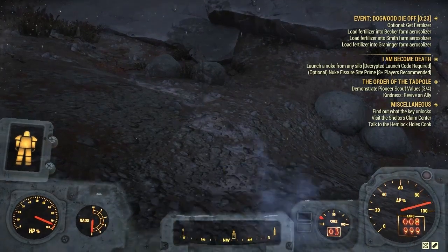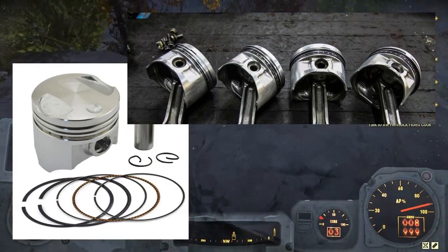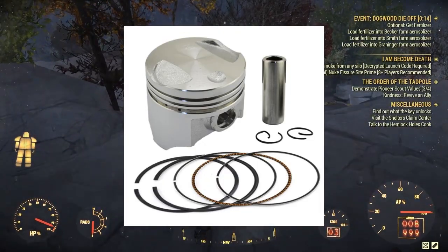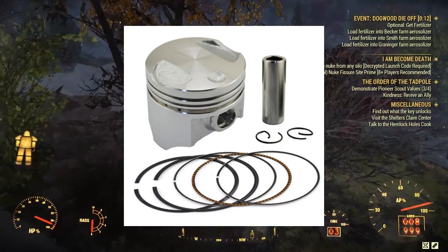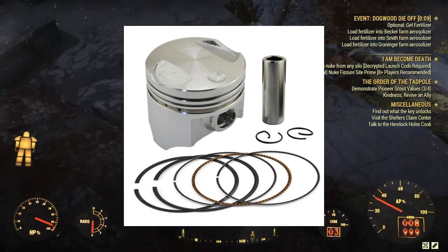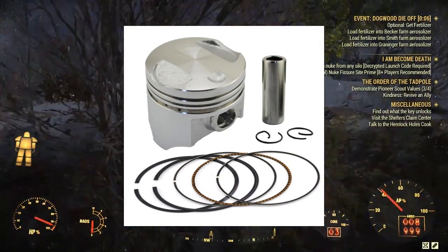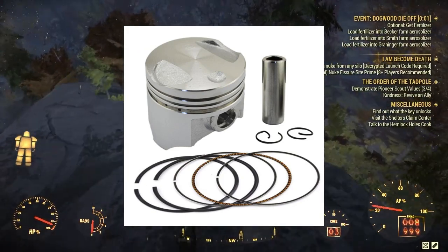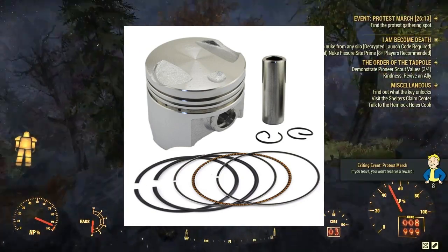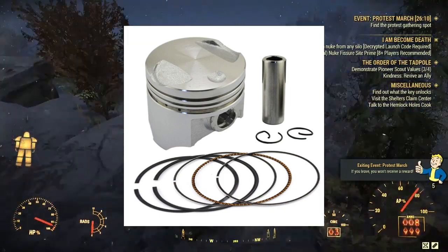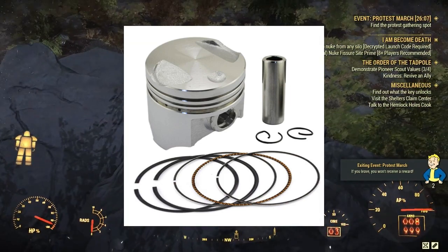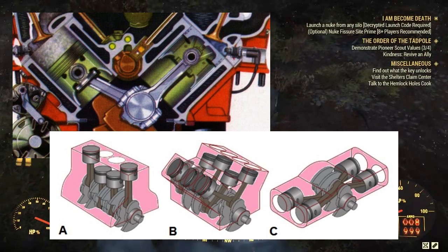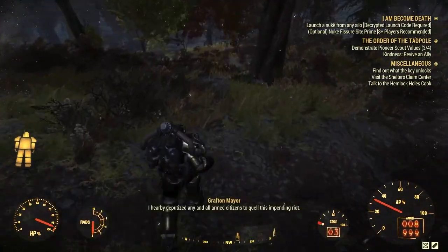And moving on from that, you have pistons and their rings. These are rather familiar terms, and more like parts that people believe should be, and do typically talk about. Pistons are basically a cylindrical, sometimes flat topped component that goes inside of the block and attaches to the crankshaft, which once again I'll be talking about further, through a connecting rod.